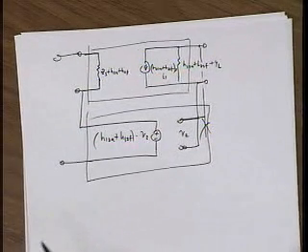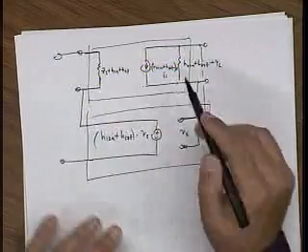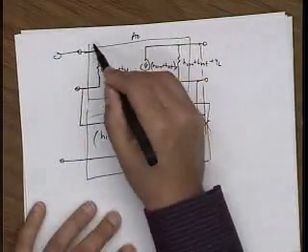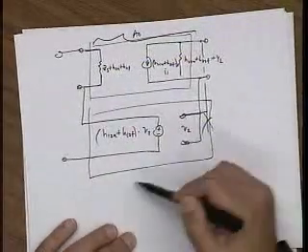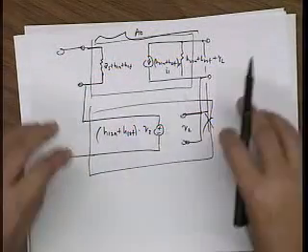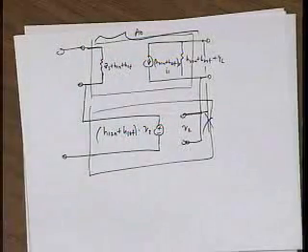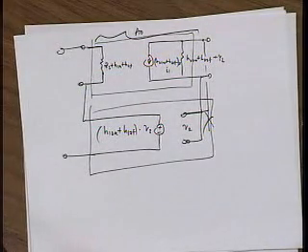It's an ideal feedback system. So I calculate the forward gain of this structure, I calculate A0 of this structure, and then calculate the feedback factor and lump all the loading of the feedback into my amplifier, and I actually can now analyze a problem.